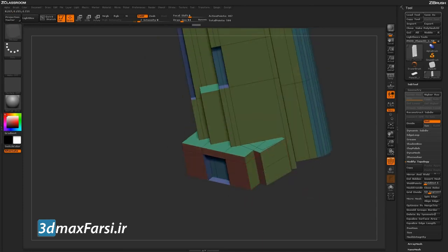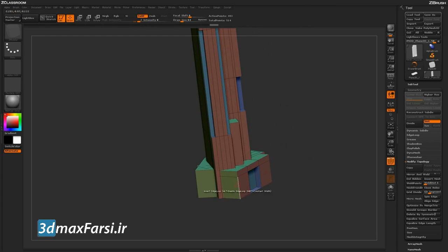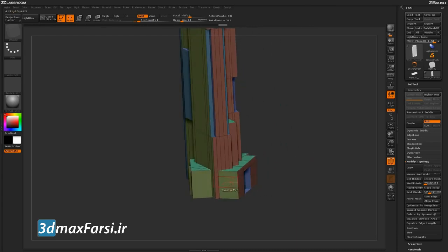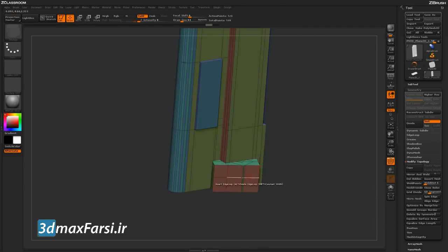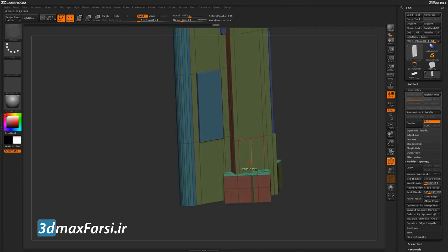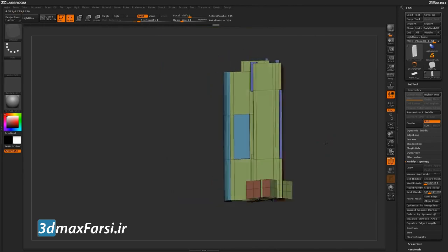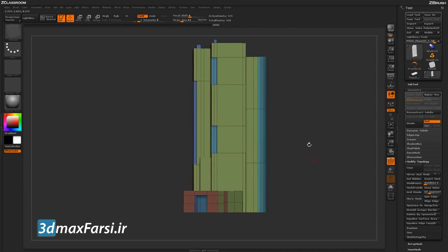And then add some edge loops elsewhere on the model. I'm going to go through now and quickly add some loops to square some of these items out to make sure I have square topology everywhere. Because we're going to populate more details on the building using surface noise, and we want to make sure we have even topology spread across the majority of our model, so square polygons wherever possible.